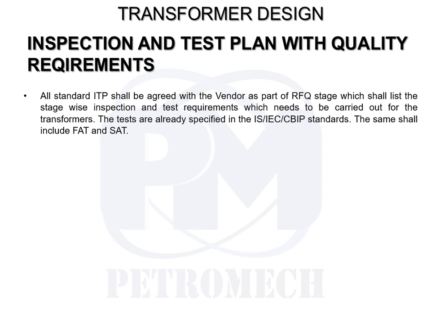And if there are any specific tests which are not mandatorily performed, called type tests, for example, temperature rise of a transformer, where you specify, let's say, a 55 degree rise over a 50 degree ambient temperature as part of your data sheet, and you want your quality team or your engineer to witness that test, right?